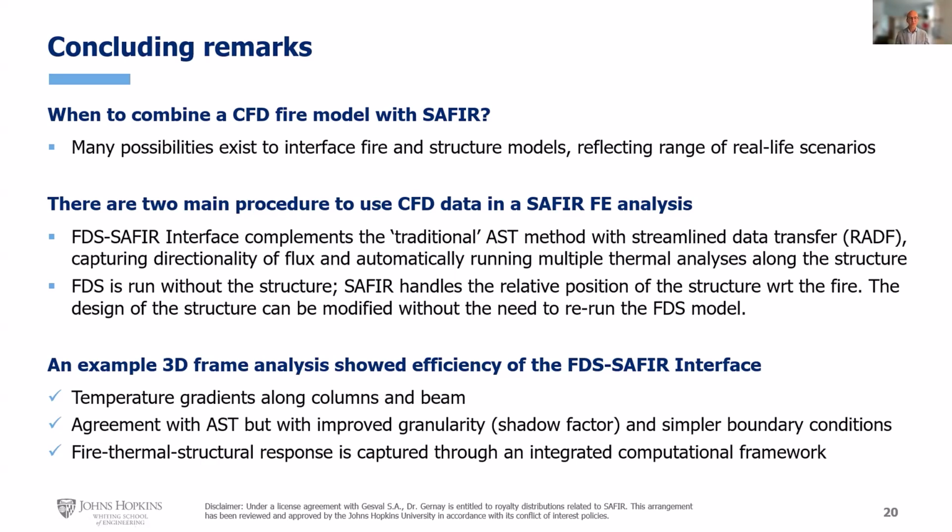Thank you, Chenzhi. So briefly, in this conclusion, just 3 points. We discussed the fact that there are many models available to model thermal exposure from fire so that they can then be coupled with a finite element analysis. And specifically, we discussed when to use an FDS or CFD type model. When we do so, there are two main procedures to use the CFD data in SAFIR: the adiabatic surface temperature method, which is treated like a gas temperature at the boundary, or the automatic interface method. Both have their interest. We've compared them and they give comparable outcomes.